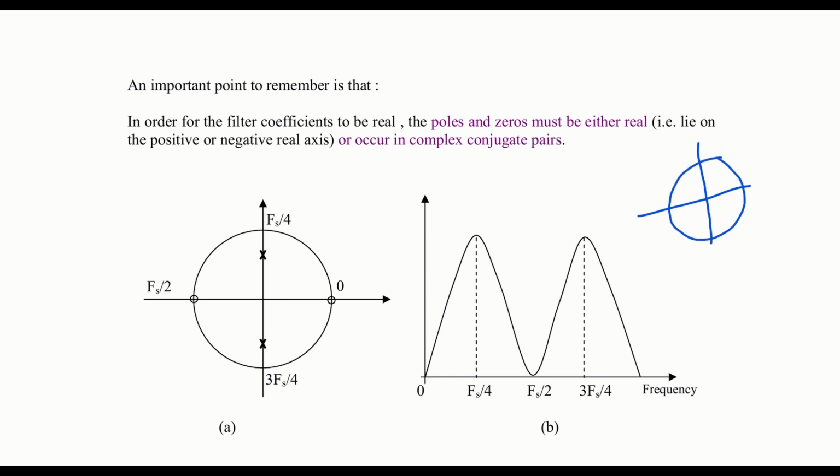So it's the z-plane, and we use the unit circle to judge the whole pole zero placement on the z-plane. Okay, so this circle you see here has a radius of 1, right? That's the maximum radius of 1, and any point which falls on it is said to be on the unit circle.